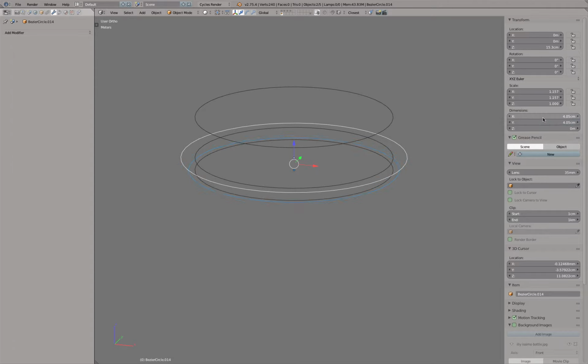And you will notice that actually the blue object got scaled, the white object did not get scaled. So what's happening? Blender kind of like, let me say it this way, you can make a selection, but always the last object you selected is kind of like the active object. So all the values we type in here this way are only applied to the active object.